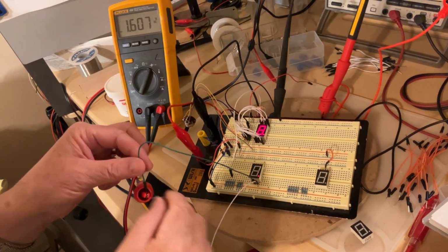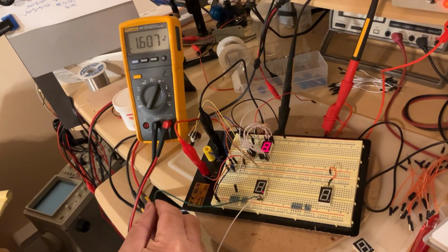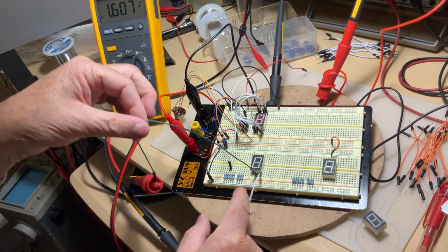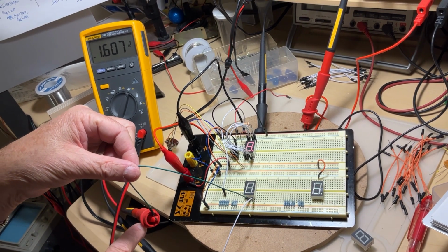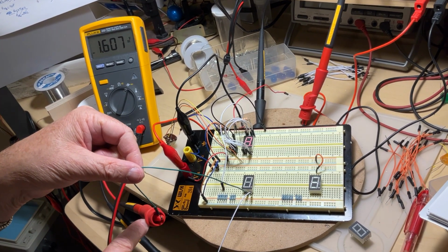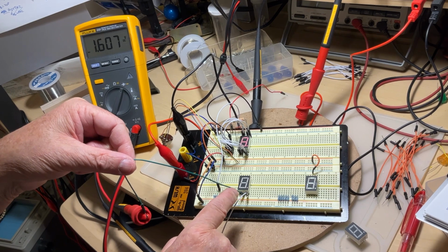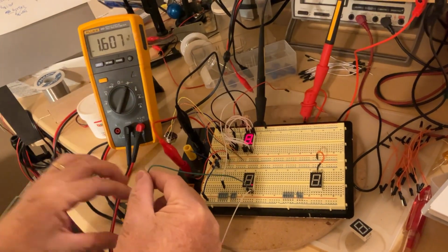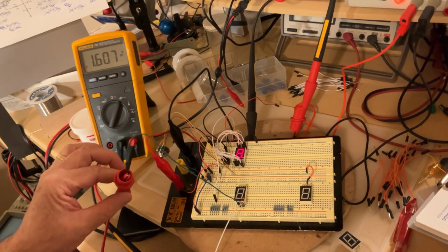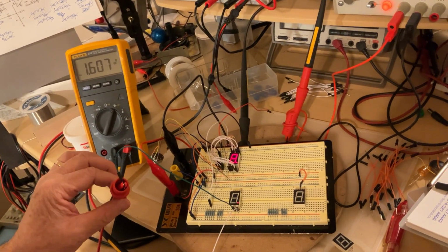The pin 3, where I have this green wire here, is connected to the red of my meter. So the red is associated with the positive. So the common is actually now, when I see the light on, a common anode, because the anode is the positive terminal of a diode.